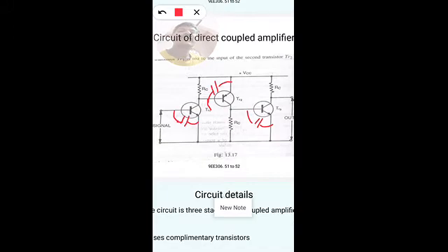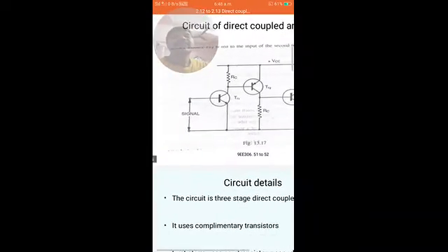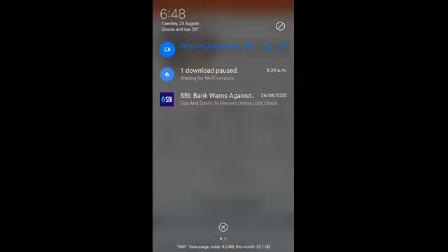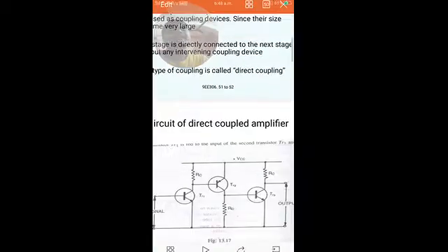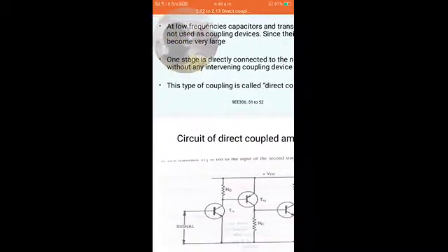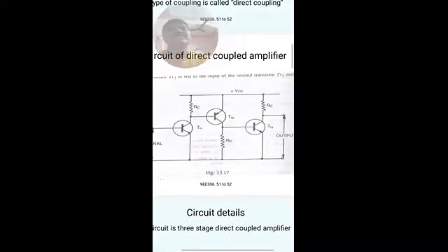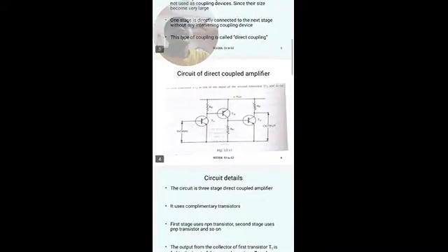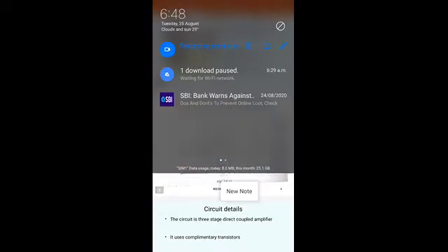Base and emitter terminal of the transistor act as electrodes or plates of the capacitor, and the air between the two terminals acts as dielectric. So this electrode capacitance will come at very high frequencies. And also at very high frequencies we have a stray capacitance, unwanted capacitance. Stray capacitance is also going to have an effect.